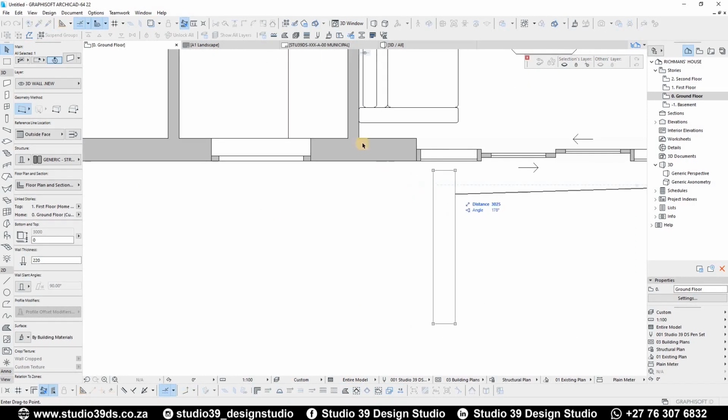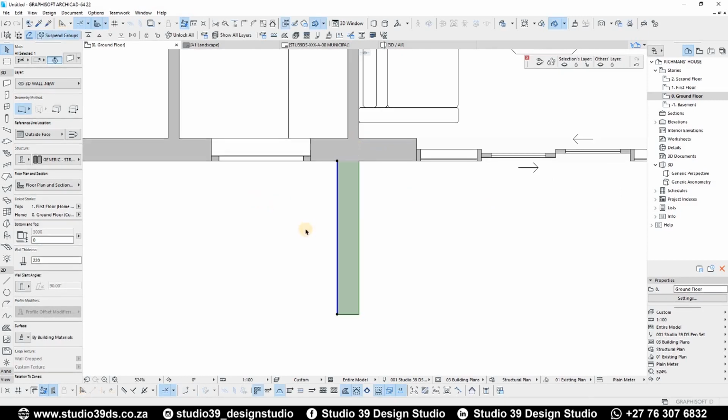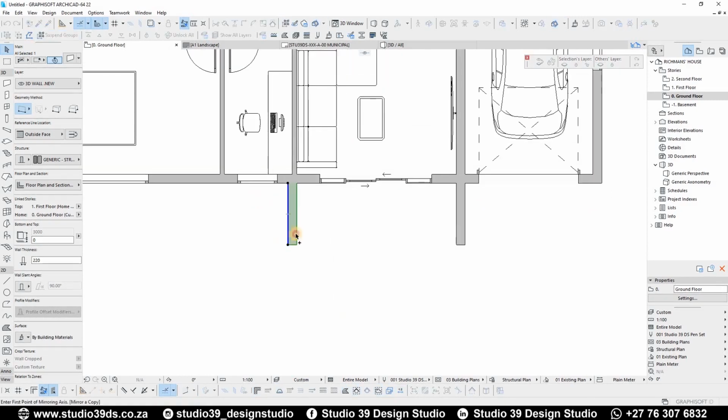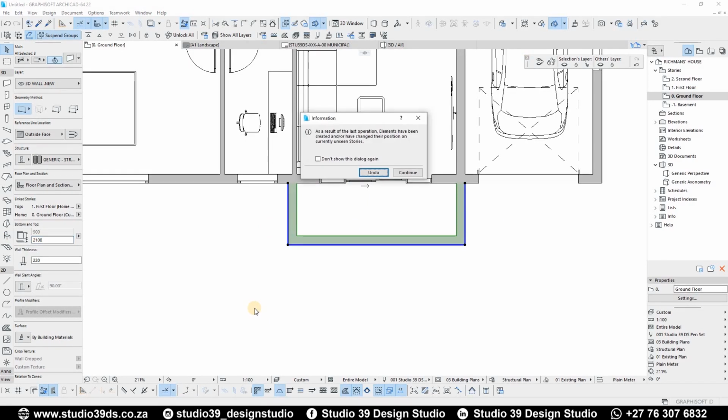So when I drag a copy to the other side, it's going to line up over there, and then I'm going to mirror it at a 45-degree angle, and then intersect both of these. Then I'm going to select, and because it's connected at the top, the only thing I want to do right now is offset from the ground about 2.1 meters, or 2100 millimeters off the ground.